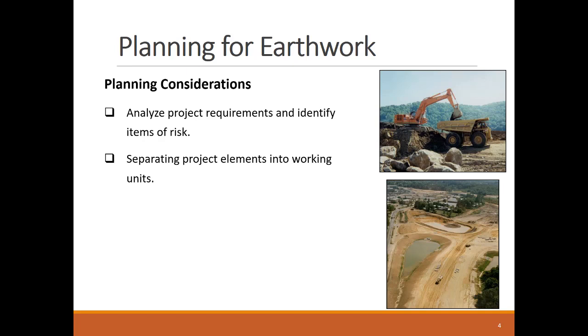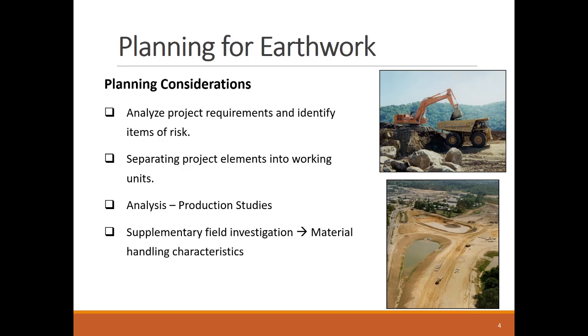Third, for each work unit and package, you need to perform detailed production analysis to achieve the lowest possible unit cost. Fourth, you need to have all information needed to understand the handling characteristics of the soil, especially swelling and shrinkage. And lastly, you need to specify the location of the soil source and disposal sites.